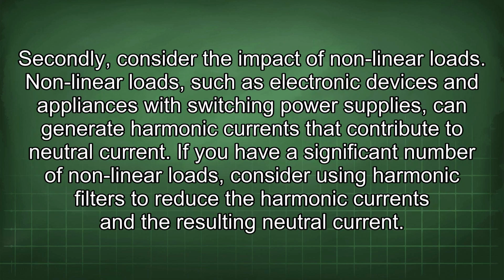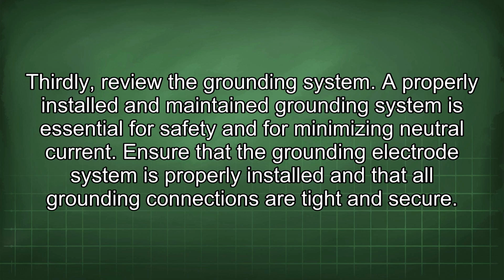Secondly, consider the impact of nonlinear loads. Nonlinear loads, such as electronic devices and appliances with switching power supplies, can generate harmonic currents that contribute to neutral current. If you have a significant number of nonlinear loads, consider using harmonic filters to reduce the harmonic currents and the resulting neutral current.